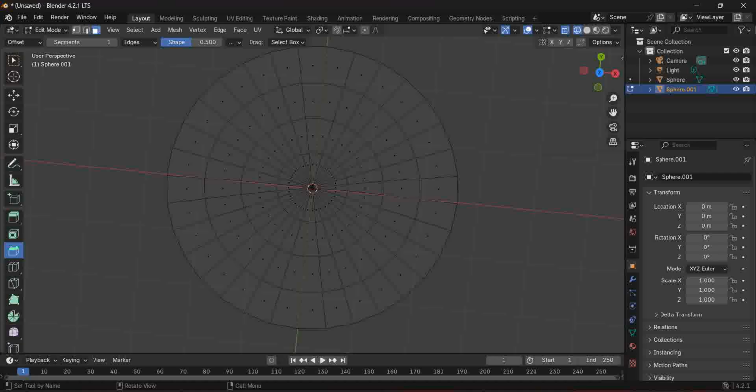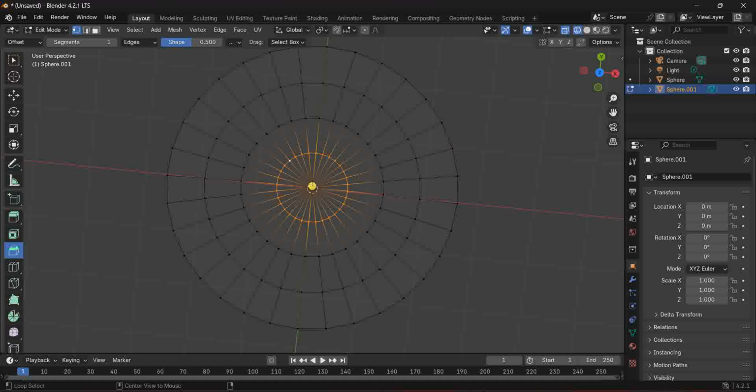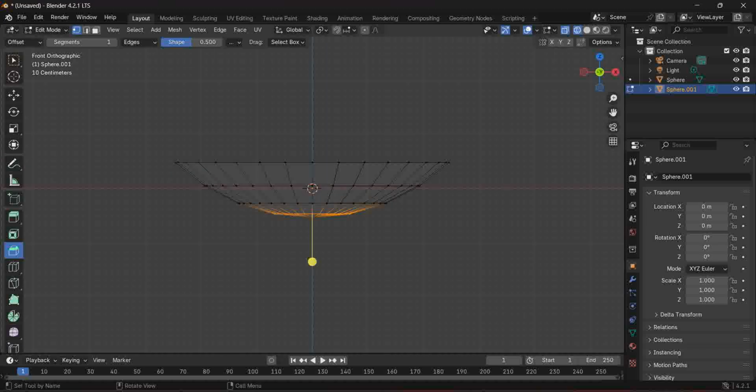Okay, so set yourself in vertex mode, and after that you just press Ctrl and select this part, this part, select these two parts. Fine. And after that again I'm going to press 1 to change my view, and then I'll move this surface. Let's see what happens.